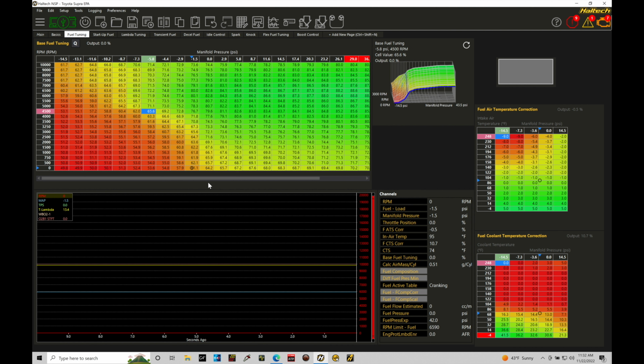Injector Dynamics actually supplies all of the data that we need, and we can download it right from their website. I'll be discussing how to do that and where to look for that information if you're running Injector Dynamics injectors. There's all kinds of different injector brands that you might be working with. You'll find that a lot of the injector data from injector manufacturers is not accurate. So we'll enter in what they can give us, but you definitely want to take it with a grain of salt because you might have to change it if you're finding that your airflow and fuel model is completely out of whack. We're going to look at what we can do to spot bad injector data and then how to correct it. We're not going to do that for this tutorial.